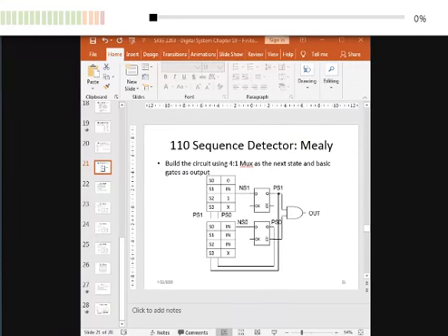Second, it doesn't really have separation of control unit and data path unit, so you don't really learn about it. So your requirement for the group exercise is you must have a control unit and a data path unit. That's one. In your data path unit, you must have different types of register. That's requirement number 2.